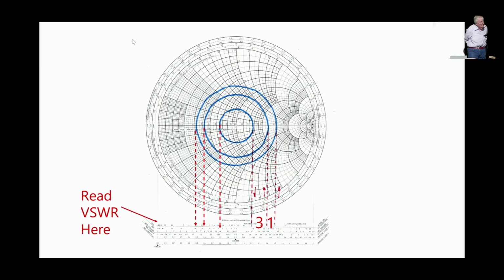But then we walk up the transmission line and lose 3 dB, and then you can see the big 3 there, or you go back up and you've got a significantly bigger VSWR. And then if it was 4 dB, it's even bigger. Particularly at VHF and UHF, you can't measure the VSWR of your antenna down at the antenna.